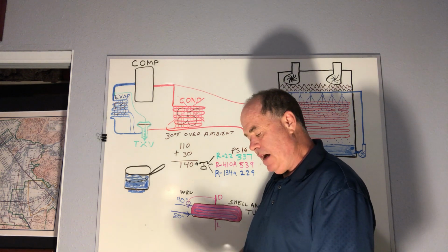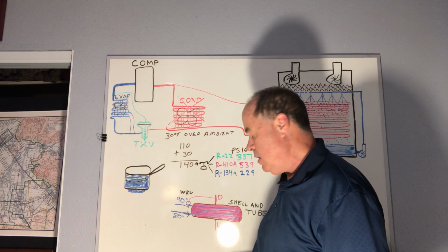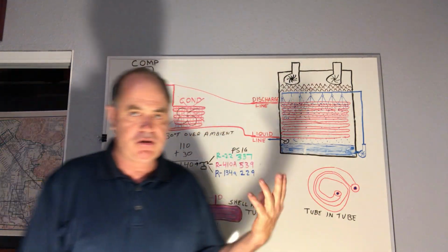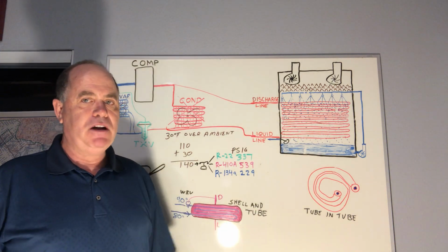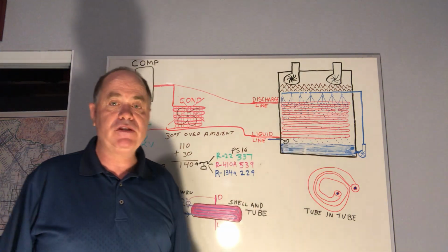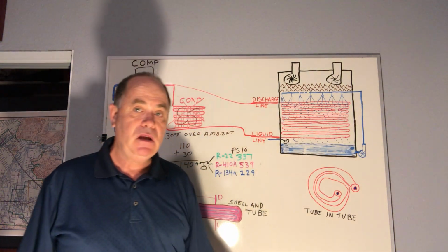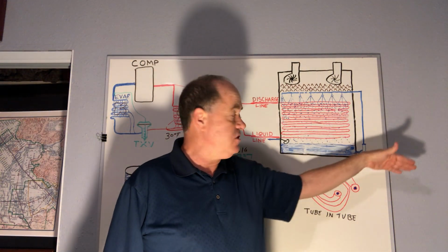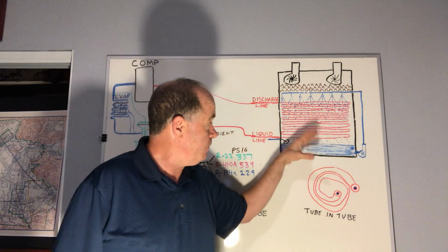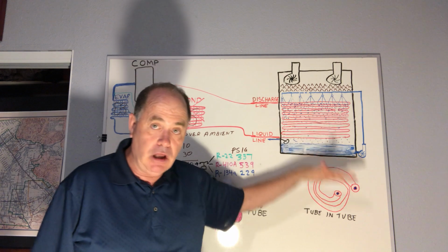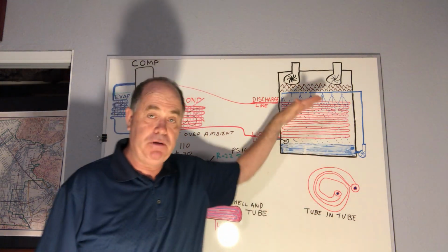And that talks a little bit about the idea of bleed off. The book says blow down. I used to run high pressure boilers. We use blow down for the boilers, but really bleed off is the better term for getting rid of some high mineral content water, dumping it down the drain, literally, when the mineral content gets too high, and then when you bring in that fresh water, it mixes, lowering the mineral content, lowering the likelihood of the scale building up.